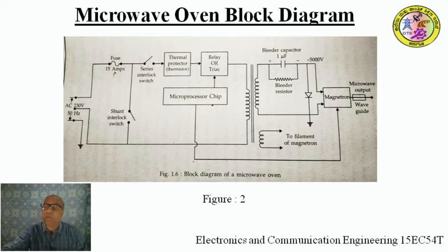As you can see here, in the conventional method of heating, heat is transferred to the surface of the material to be heated by conduction, convection or radiation, and into the interior mainly by thermal conduction. In contrast, in this microwave heating or dielectric heating or any other frequency, heat is generated directly inside the material. Heat is not generated outside, but directly inside the material the heat is generated. Therefore, it is possible to obtain a much faster temperature rise than conventional heating.